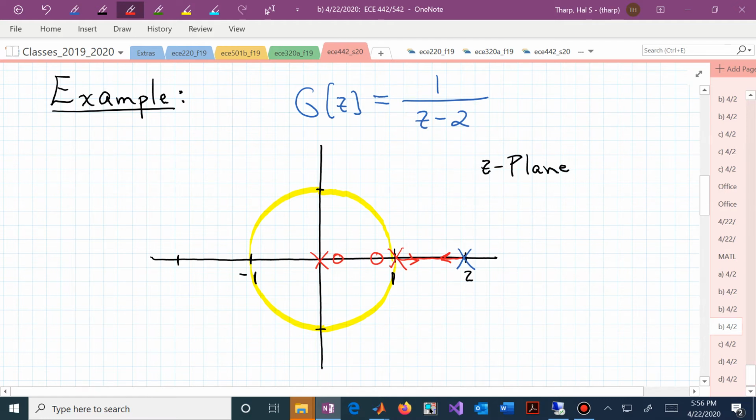Now we have this real line segment as a part of our root locus. Now these may branch over and get further into the interior of our unit circle, or it may provide us with the percent overshoot behavior that we're looking for, or the time to peak behavior that we're wanting, or settling time spec.